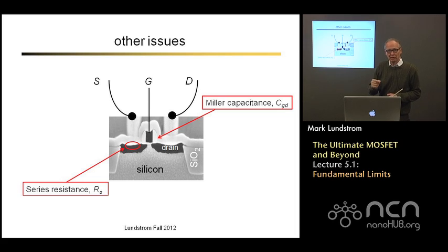So the electric field lines from the two will form a parallel plate capacitor. That's a parasitic capacitance between the input of the device, the gate, and the output of the device, the drain. When you put a capacitor between the input and the output of a transistor, it's especially bad. So these parasitic effects, as you get smaller and smaller, are also important factors that challenge scaling.